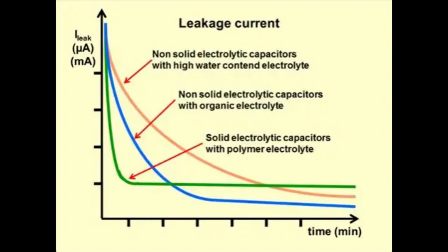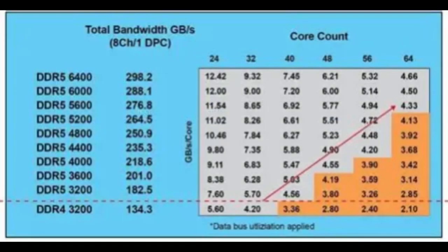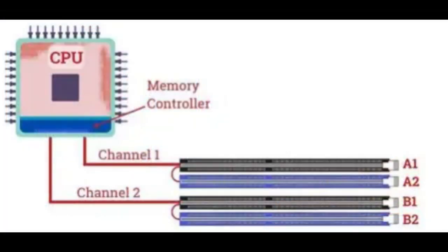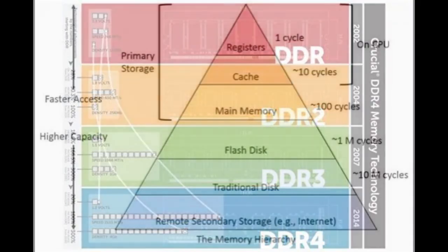And inside of a RAM chip, billions of these cells are arranged in a 2D grid. Rows equal word lines, columns equal bit lines. When the CPU wants data, the memory controller: 1. activates a row. This then opens an entire page of memory. 2. selects the column containing the exact bit or byte. 3. reads or writes the charge. 4. pre-charges the row to prepare for the next access. Now, this ability to jump directly to any row/column is why it's called random access.